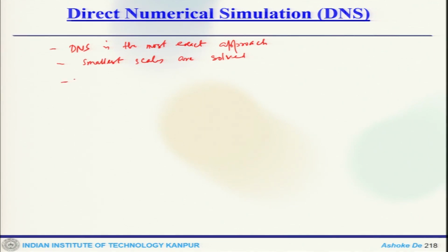So, the DNS simulations scale with Re to the power of 9/4, where Re_L is of the order of 1% of Re. So, if you take an example of a simple flow past a cylinder, this will take some 8 million cells. But as I said, given the current processing time and memory, it is still possible.